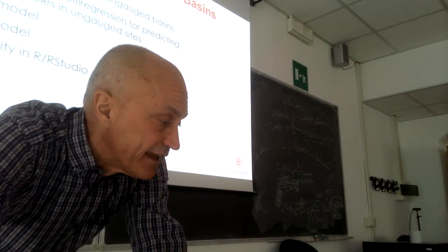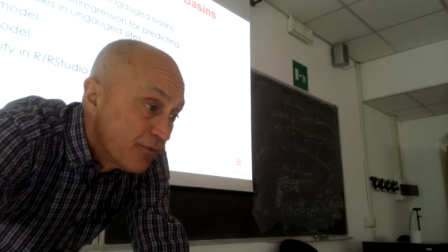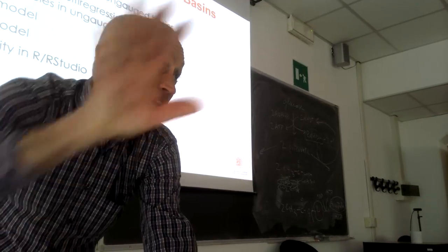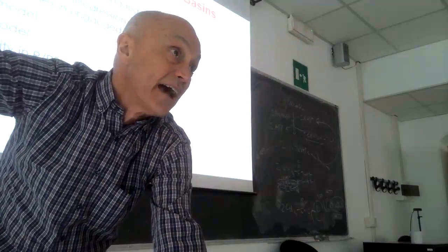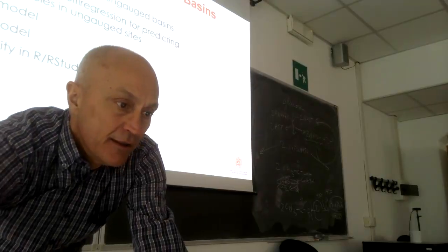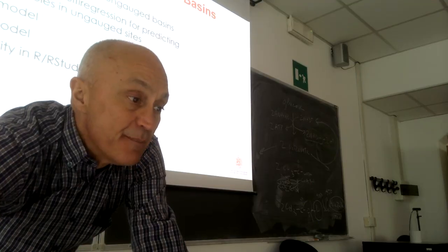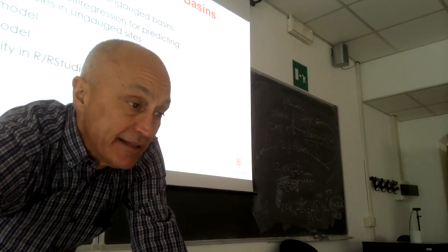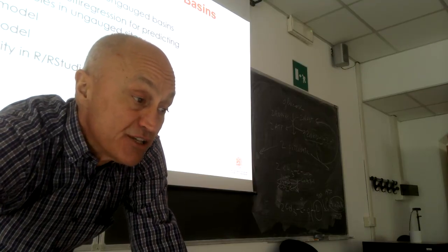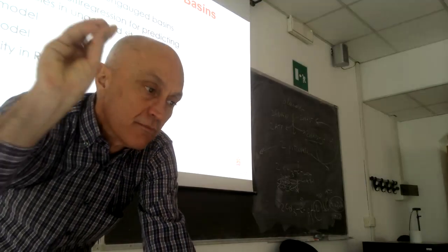So we will see how a flow duration curve can be predicted using data collected in a region. We will see how to set up particular models that predict stream flow indices based on catchment characteristic. And then we will see how this catchment characteristic can be, let's say, derived in a GIS environment. So, prediction in ungauged catchment through regionalization.